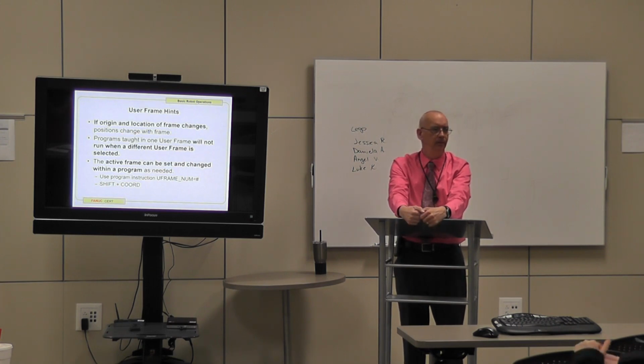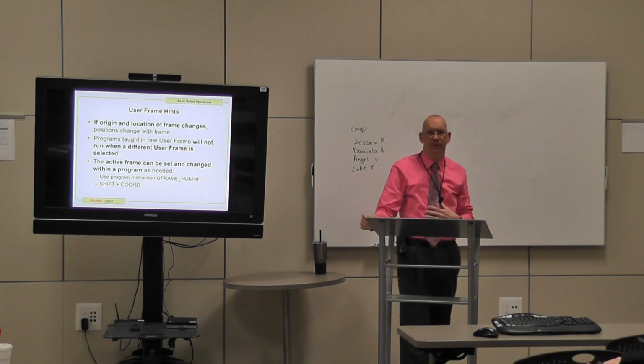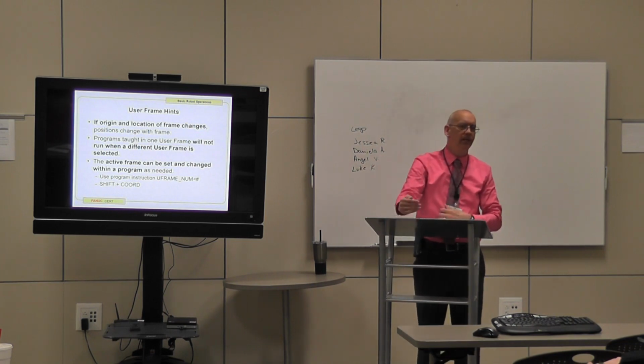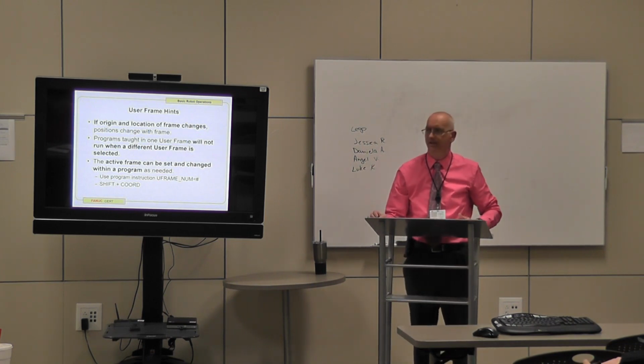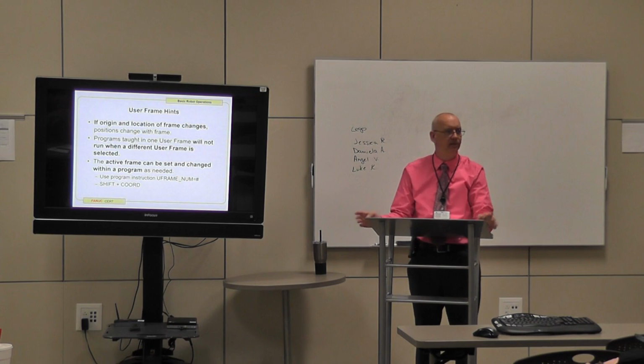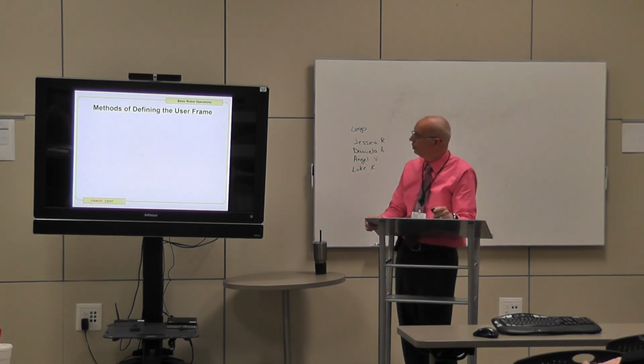Okay, that make sense? And if we do not assign a user frame within the program, in order to run that program in auto, we need to manually assign our user frame when we go to run that. And this is why it's important that we put it in our program, because we just make it happen. It just happens.